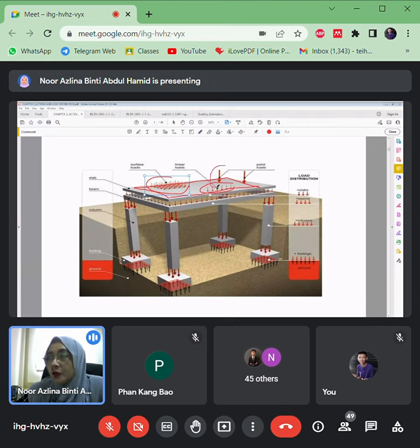Okay, and then the point load here might be from secondary beams, right? Like crossings that are supported by the beams, or there might be columns. Okay, there's a column within the slab's area. So all of the columns and foundations here are considered as applied point loads.